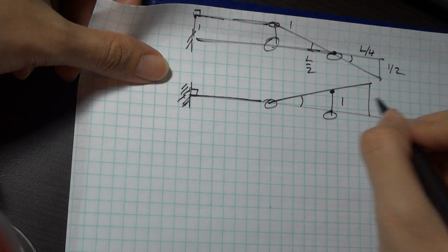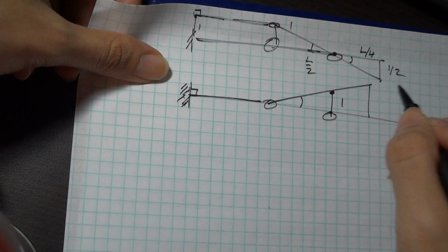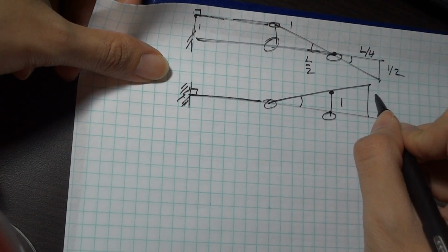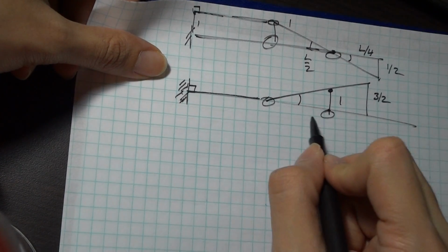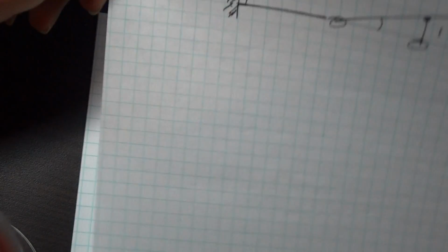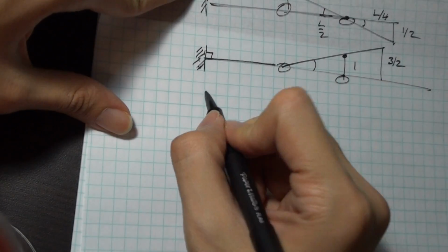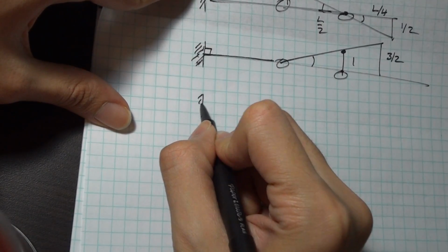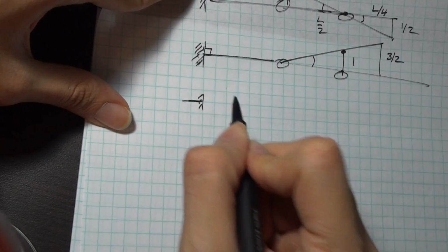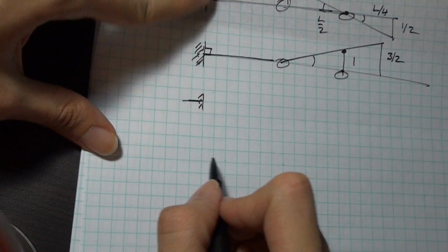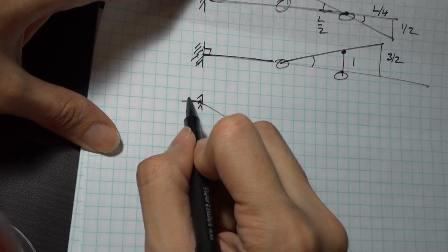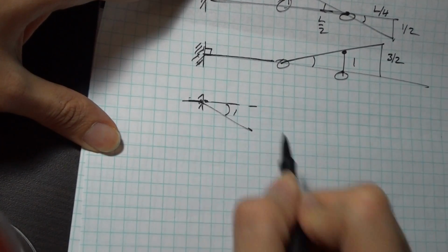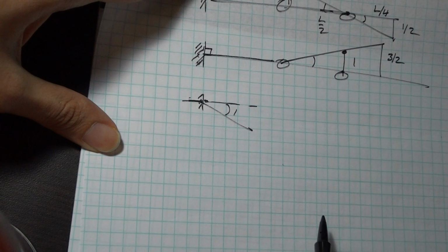I should not have marked that angle, but this is 1. And again, this is going to be 3/2. And you can use a little bit of geometry to figure this one out. The moment at A. In this case, when I'm working with a cantilever, I can pretend that I have a little arm that's buried within the cantilever. And I'm bending A with respect to that arm. So you can see that I'm bending A with an angle of 1.